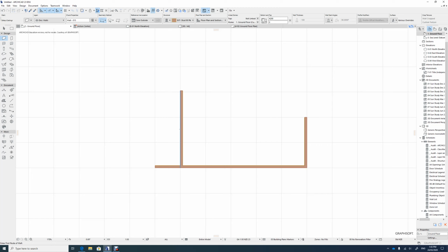While I'm here, some of you also might be struggling with, if you've just opened your ArchiCAD file and you've started drawing walls, it's come up as boxes. Don't forget up here, this is where you change your method of wall. So I already had it on singular wall. You just left click and choose some different options, or use G on your keyboard to change through the different options. So there's circular walls there, a triangular wall, but there's a singular wall. There's your joining walls. So if you want to keep going until you finish, there we go. And there's your box walls.